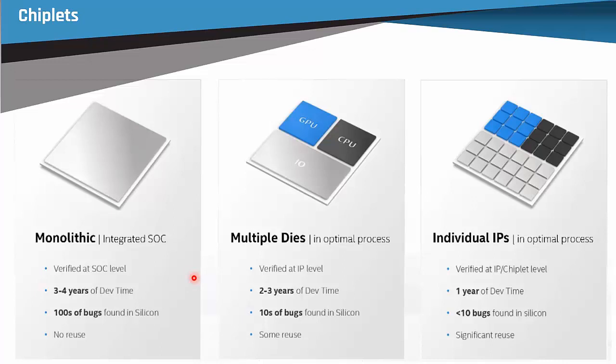We'll try to put several chips really, really close, tightly connected, and have really fast interconnect between them. And the way to do this is we take an older process like 65 nanometers and use it as a substrate that mini chips are going to go on. So we don't do any crazy fabrication of transistors on that substrate, but we do make our backend layers and through silicon vias that enable us to make the wires, to print out the wires with a VLSI process instead of a board design process to connect between chips.